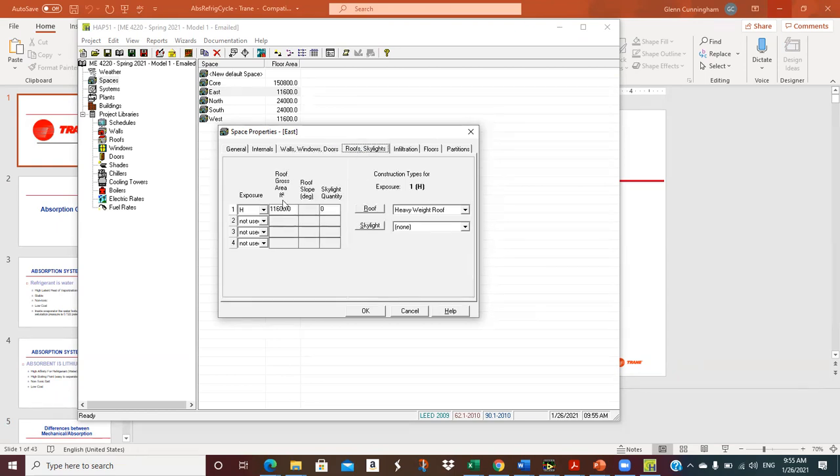And then the roof, I was lazy. If it's sloped, you put in what compass direction the normal coming off the roof would point. Would it point north or whatever? This building has a sloped roof, so this side's actually pointing north, and I think that's south. So I'd put in half of it north and half of it south, and slope and pitch and area, pain in the rear.